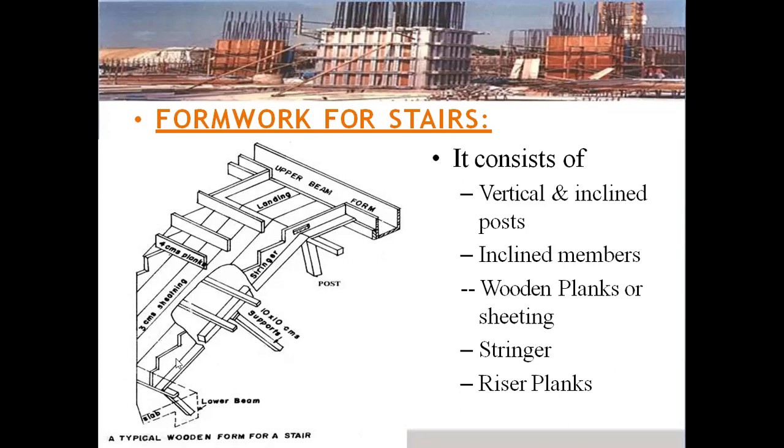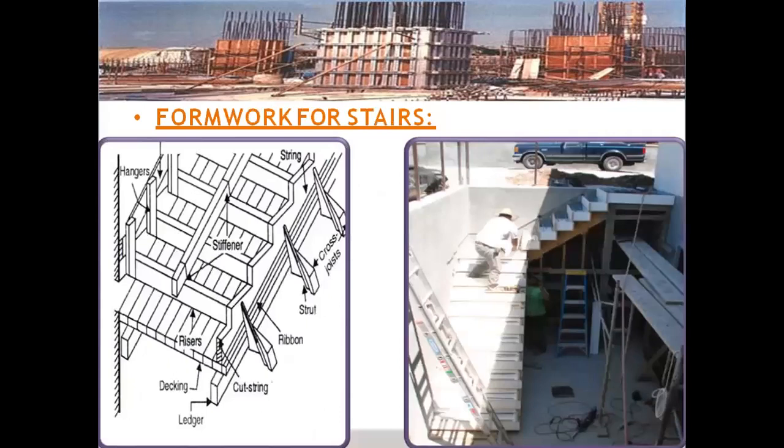This is the support post to support the fluid concrete which has been poured onto the landing area. So the amount of load is high, so that these posts can support the material. These posts support the material. So, the formwork for stairs.